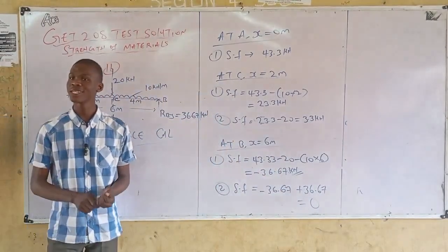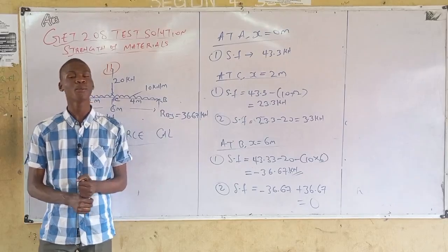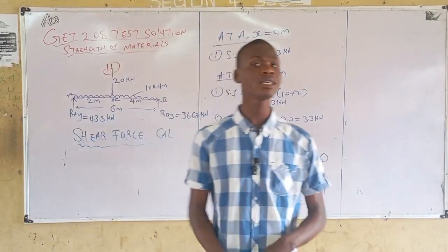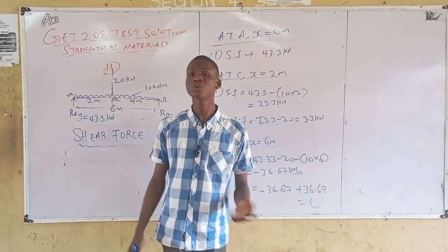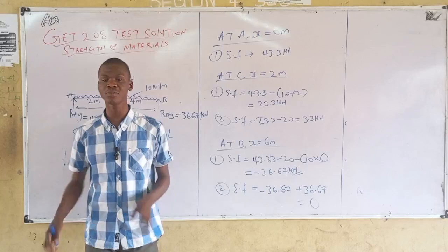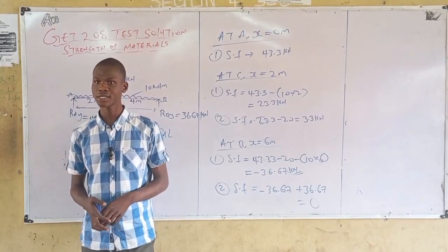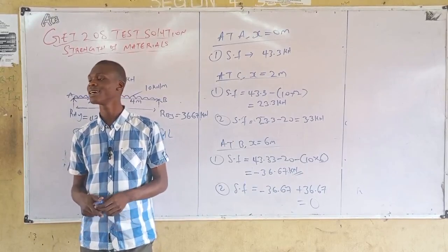With this, I'm very sure that my shear force is correct. Why? Because shear force must end with 0. It's very easy, whenever you are solving, to know that you are correct. Even before submitting that script, that confidence will be there, 100 percent. So now that's it.